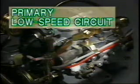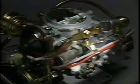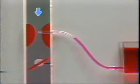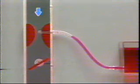The primary low-speed circuit supplies the air-fuel mixture when the vehicle is idling or traveling at low speeds. Here we will use a model to demonstrate. As you can see, the throttle valve opening is very small when the vehicle is idling or traveling at low speed. The amount of air allowed in by the Venturi is small, insufficient to draw up much fuel.